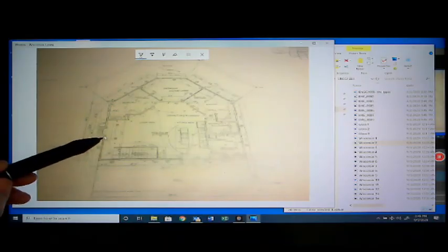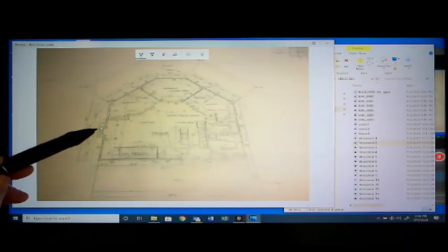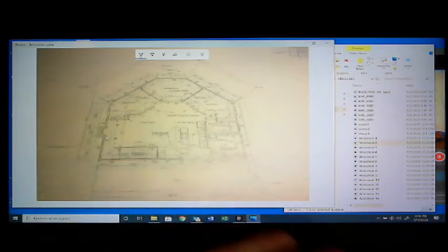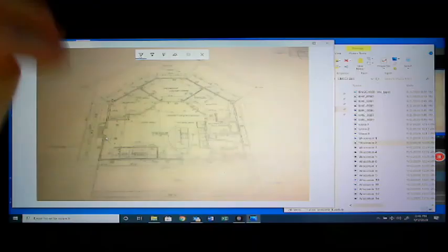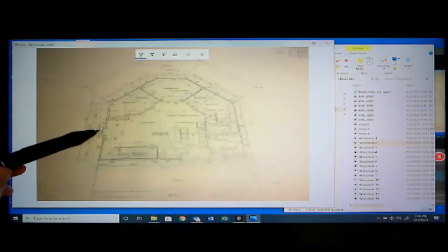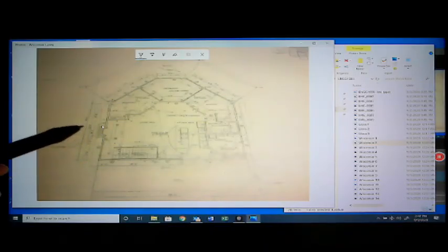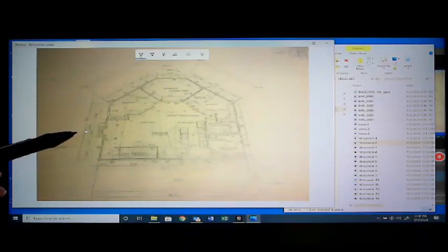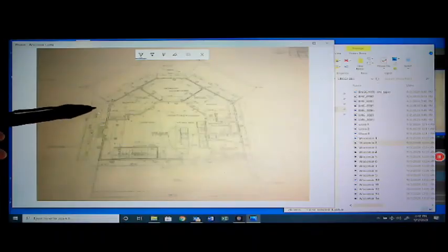Here we have the fireplace. A floor plan is at a 4-foot level. It's a slice through the building, looking down at what you see. This is the cross hatching, from basically cutting it, so that you're seeing the surface of all the cement or brick or whatever that's there. And you can see this is the outer covering on the fireplace. Anyway, you can see the size of the fireplace there, and so on and so forth.